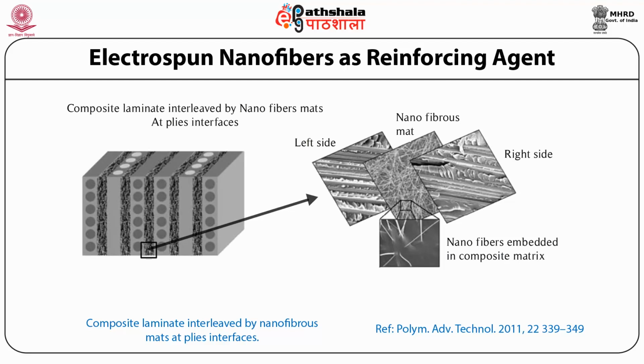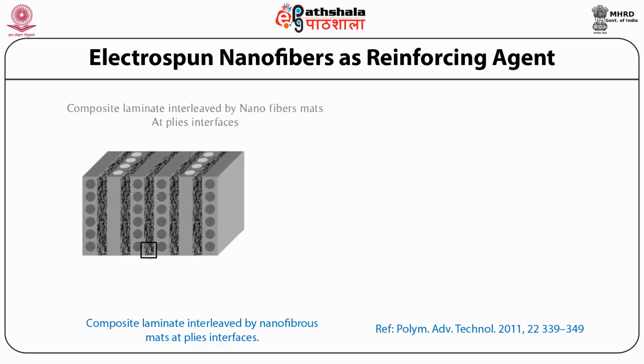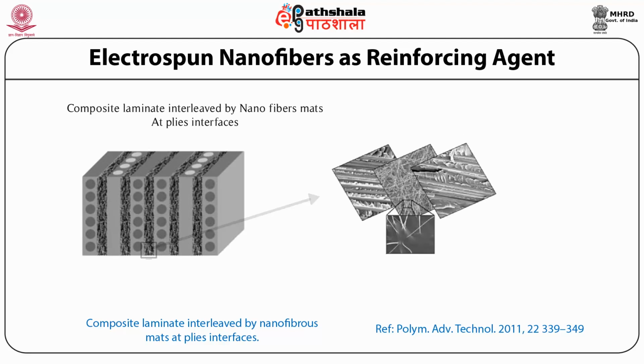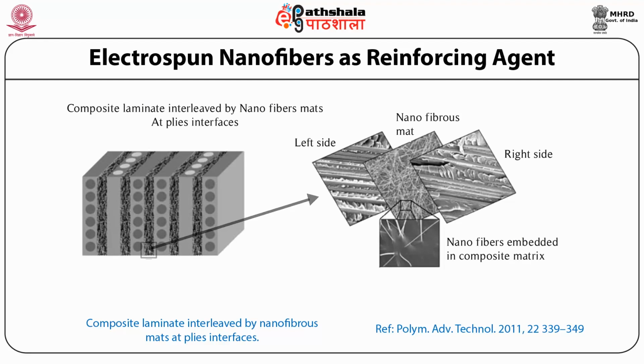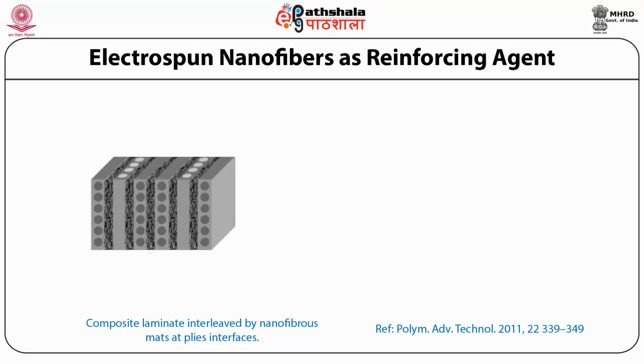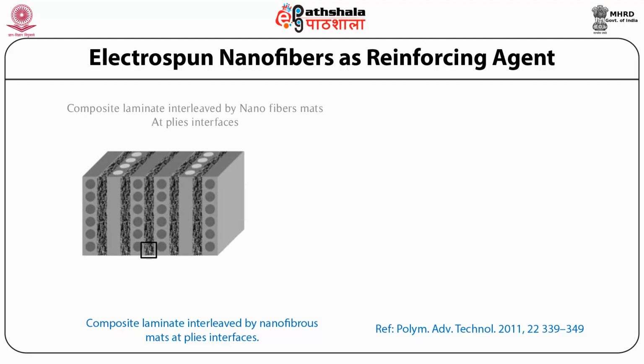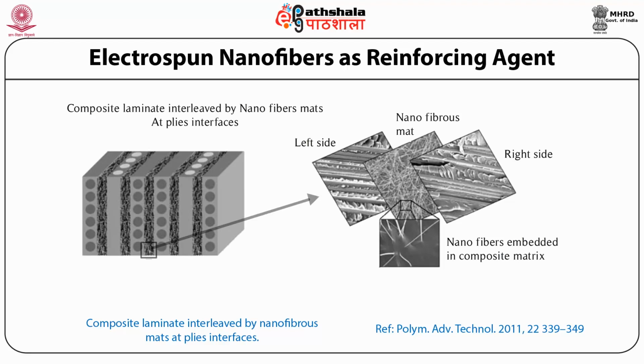With the aid of these fiber reinforcements, the composite material exhibits superior structural properties including high modulus and strength to weight ratio. Prompted by these practical applications based on traditional fibers, electrospun nanofibers have been investigated in fiber reinforcement as well, driven by their better mechanical properties than bulk fibers.